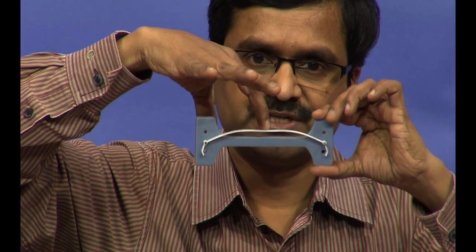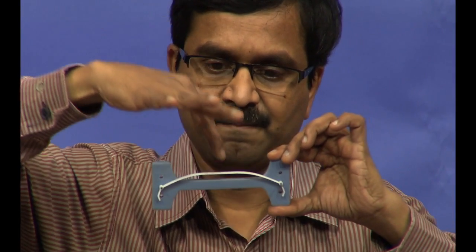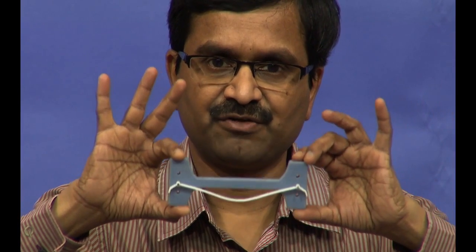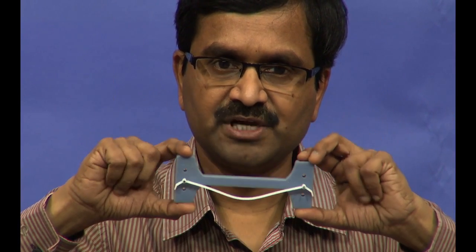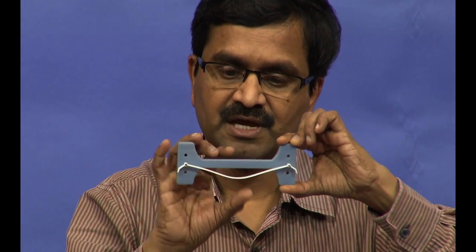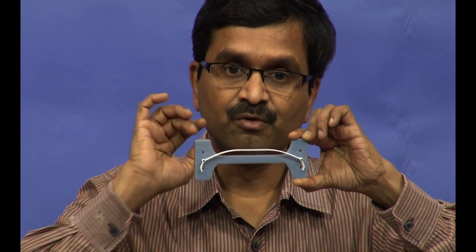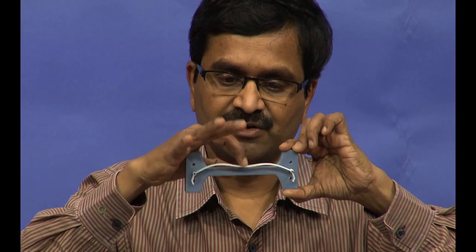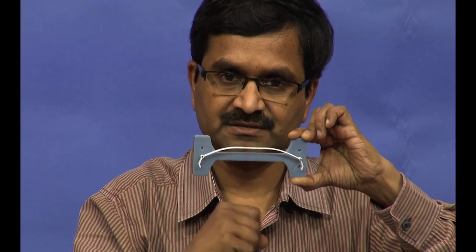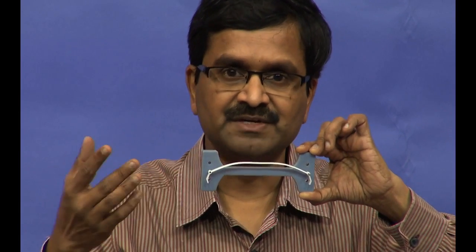Now, I apply a force in the middle. This is one stable state where we are. Now, when I apply a force, it will go to the other state, that is the second state. It is stable, with no external force, that is the definition of bistability, that is, it has two stable states without external force acting on it. Now, when I apply a force back, it of course comes back, you can see how it actually snaps, because this is the as-fabricated load-free or stress-free state. Now, when I do this, it is under stress, that is why when you apply force it just snaps back. When something is under stress, it won't relieve its stress.